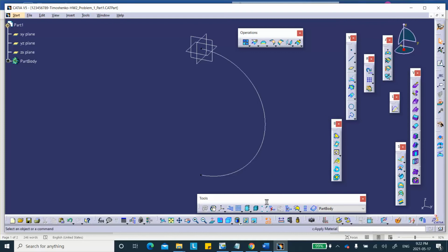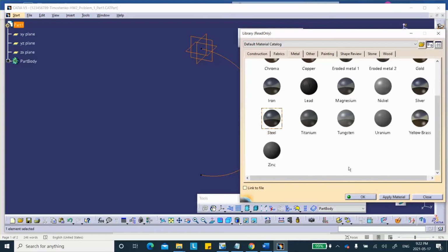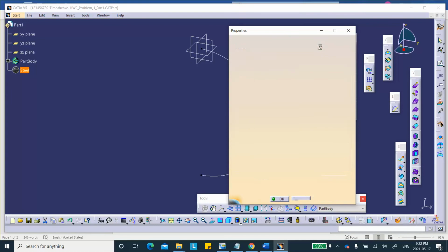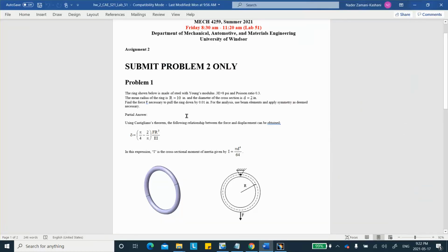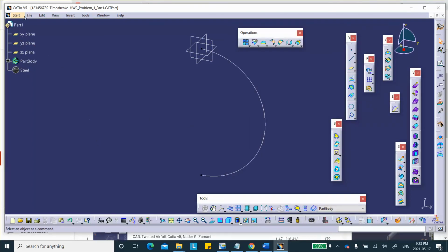Made out of steel. If necessary and you need to change it, go there, double click on this, analysis. I don't know in this problem, but you don't have to submit this. I've used different values here, so I can change it here if you insist. It's very close to that, 310. Instead of 3, it was 2.9, and this is 0.3. On the test, if you are asked to change, if you are given values that are not the default values, otherwise it says default values, so you don't have to worry about it. Say good. Now we're going to save this.